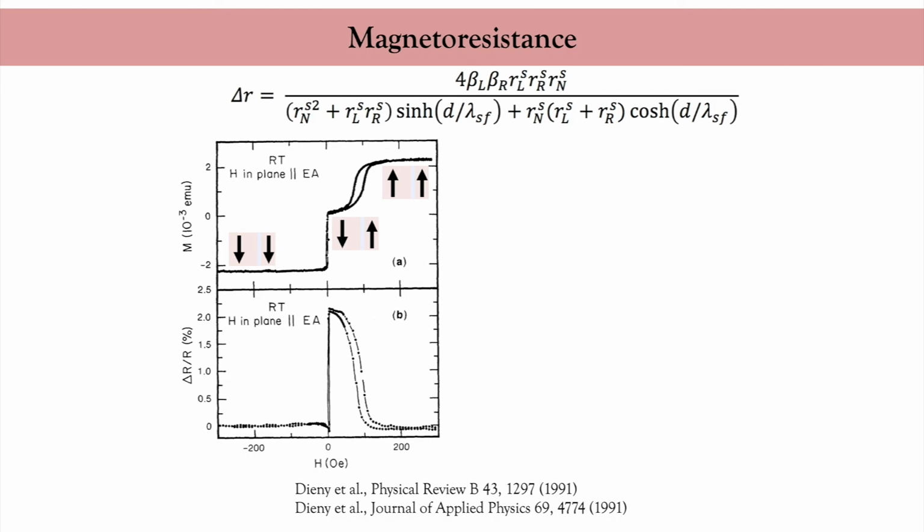both magnetizations pointing upward. The bottom diagram shows the corresponding resistance of the slab, and you see that when the magnetizations are parallel to each other, you get a low resistance, and when they are anti-parallel to each other, you get a high resistance. Technologically, we are interested in this loop, which is called the minor loop. In this region, one can reversibly switch between high and low resistance states using reasonably small magnetic fields.